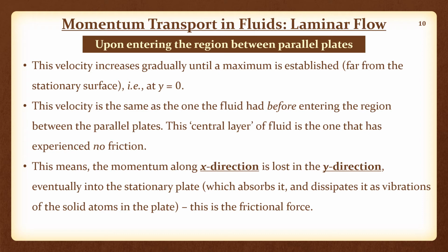Whereas when it comes to fluids, the cohesive secondary bonding between the fluid planes or laminae is possibly weaker than the wetting or adhesive forces between fluid and a solid surface. If such a situation exists, then there will be no slip at the wall, and that means the velocity of that particular layer of fluid at the surface becomes zero.